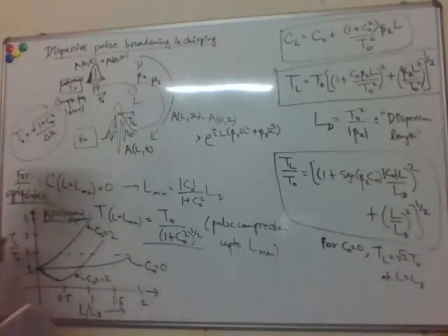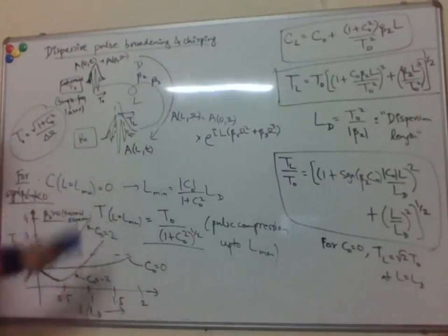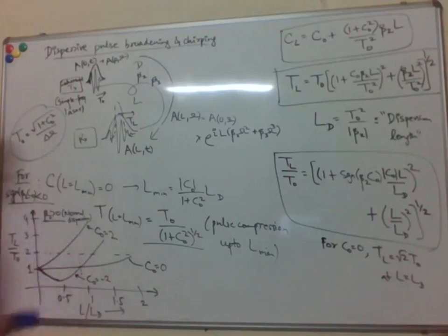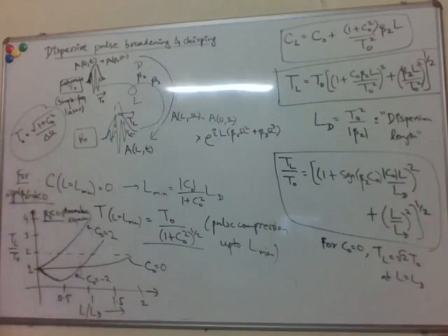And you get the same curve if I switch the signs, right? So if I make this anomalous dispersion, recall normal dispersion happens for your conventional step index fibers below 1.3 micron. And above 1.3 micron, which is basically our telecom range of operation, there is anomalous dispersion. So beta 2 becomes negative. Right, so these will switch.